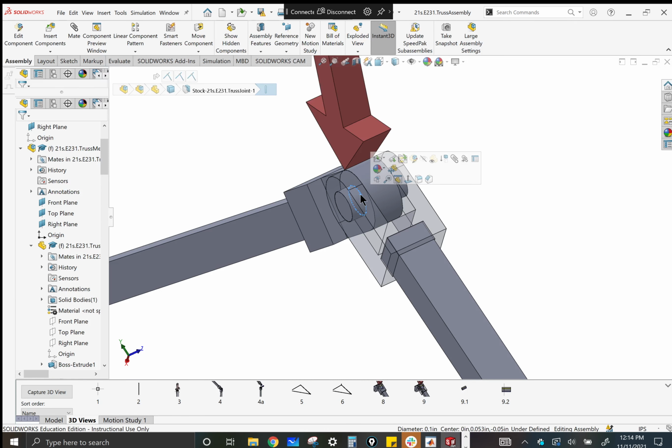So it's completely different. In other words, we're using the same equation, but we're going to get a completely different result with the same material. Interesting, right? It's because of the orientation of the force or the load to that material. Does that make sense? And when we're calculating this, we need to consider what part of the pin is taking the load. In this case, it's what we call double shear.